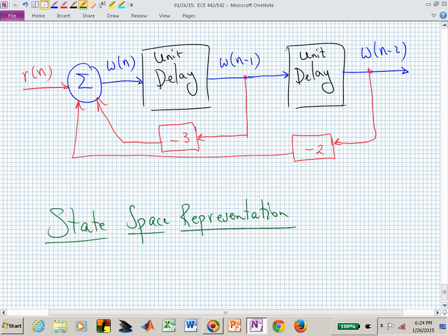What was going into the integrators were what we wanted to integrate so that the output of those integrators produced something related to a state space representation. What's in a state space representation? State variables, key, ding, ding, ding. We want to label the outputs of our integrator blocks as state variables. We do the same thing here. We want to label the outputs of these delay blocks as state variables.